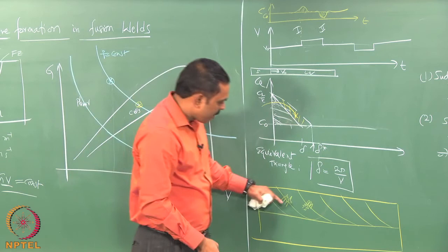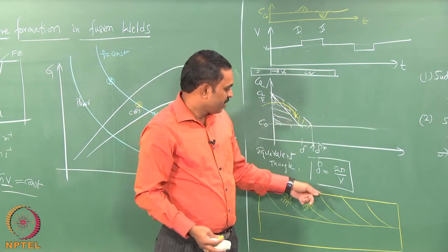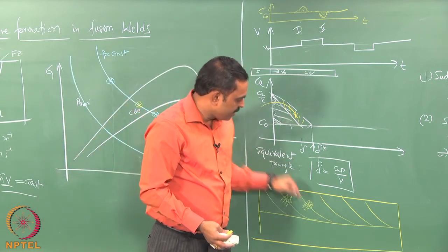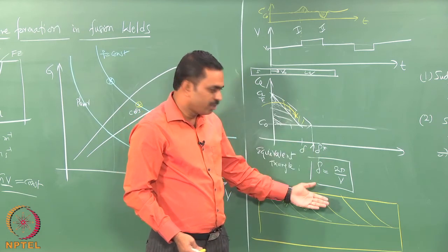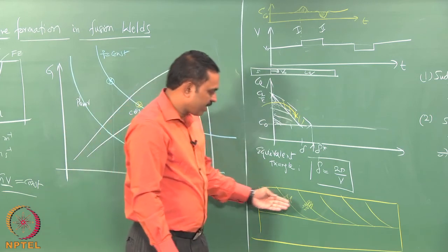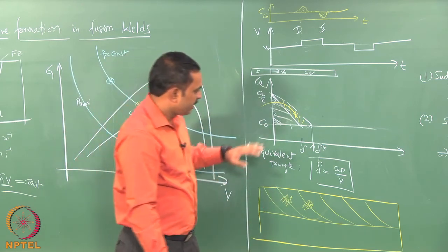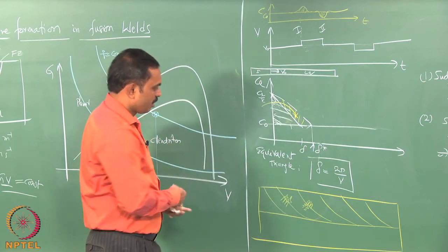So, you see a microstructural change corresponding to every disturbance in V that you have had, and these are microstructural features that can tell you also the shape of the fusion zone in the longitudinal section, which is valuable because you can analyze the growth rate and the segregation based upon those profiles, but it also tells you that the microstructural changes are actually capturing the process conditions quite closely.